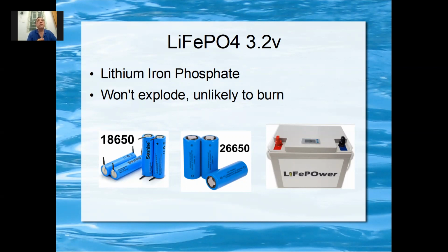And the problem comes with 48 volt. Because for 12 volt is 4 cells, 24 volt is 8 cells, 48 volt is 16 cells. Okay, but sometimes you put 15, you still get 48 volt. But you put 16, it's actually 50, 52 volt like that. So it's actually much more.